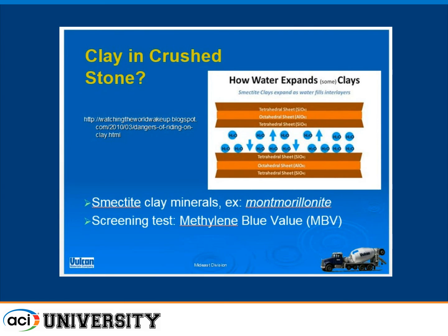But anyway, there's this clay mineral group called smectite. And the worst actor in that family is montmorillonite, okay? This is a depiction of what that is. You've got sheets of molecules, and in between the sheets of molecules is just an open space for water molecules to migrate into. And there's no end in sight, something like, I don't know, it expands 4 or 5 times its volume.